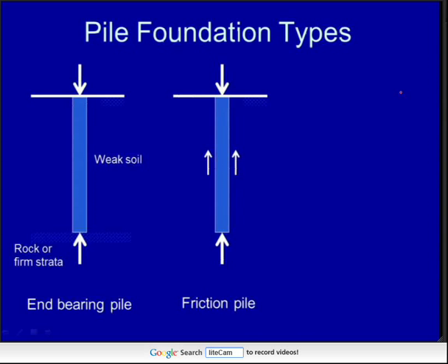One of the techniques we can use to support that hole during construction is to fill the hole with a drilling mud, a bentonite slurry. These muds have a high density, not quite as high as the soil itself, but higher than water, and they are thixotropic. So when they're left undisturbed, they have shear strength. But as soon as you put the auger through them, they lose their shear strength. So you can drill through a drilling mud and support the hole with the drilling mud pressure.